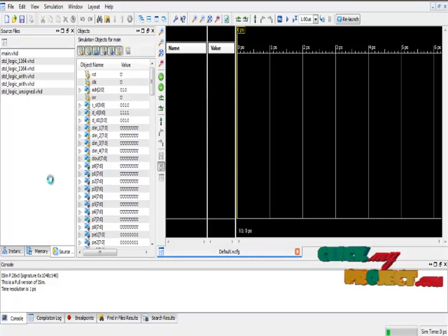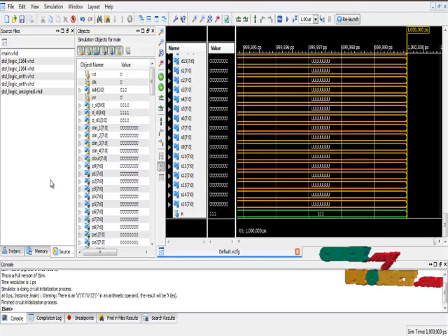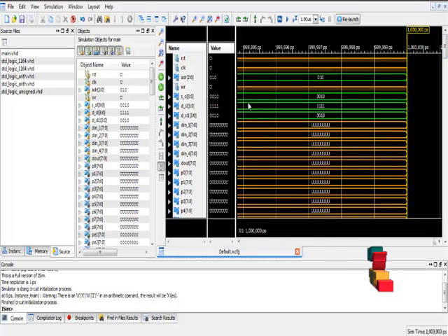We give the input for clock, reset, and write, and at the same time we mention which selection line we get the output from. I have explained the reset. First we give 1 and 0 as the reset, and by default we give the clock and address. This address line chooses which data is going to the routing process. I have chosen 010 in the program.